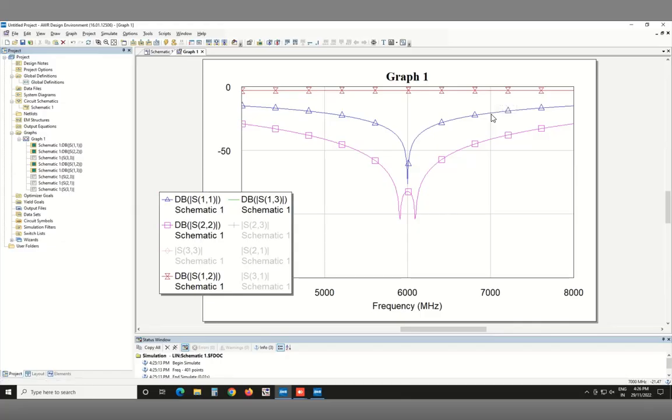And if you are allowing a little bit more, if you go all the way here, this is still minus 15 dB. Still most of the power is getting transmitted. The S22 is always better than that. In fact, here it's still minus 30. So S22 is almost irrelevant to worry about.